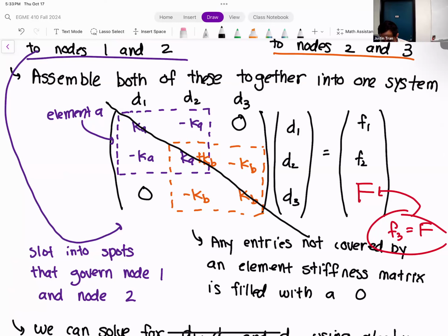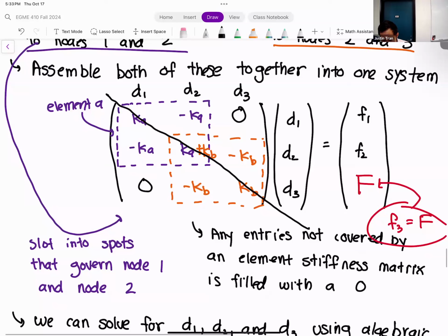And so the last thing that we did here was that we needed to modify this matrix according to our boundary conditions. Because what we said was that this matrix by itself we can't actually solve it yet because the matrix is symmetric. Our right-hand side vector right now is kind of undefined, and so we need to apply boundary conditions in order to make everything good.